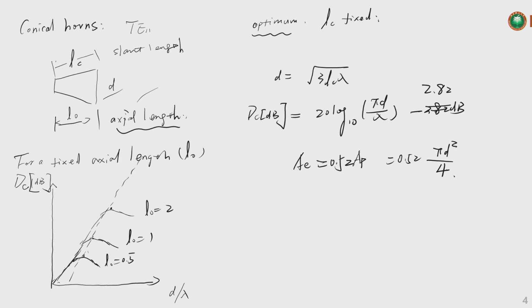And sometimes, if we just follow this rule and we want to design the antennas, if the required directivity is too high, we need to set the axial length or the slant length very long, and maybe under some limitations on the application scenarios, a certain kind of antenna is difficult to fit or to use. The method we can use is a lens.